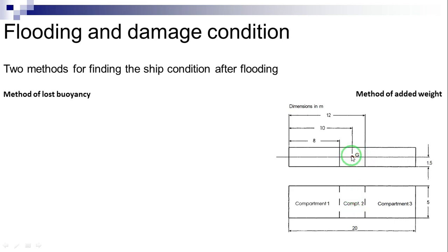Thus, the flooding of compartment 2 produces no trim. Also, the compartment extends for the full ship breadth and its flooding produces no heel. The only change of position is parallel sink. Thus, the complex calculations necessary for conventional ship forms, for large trim, or for unsymmetrical flooding do not obscure the principles, and it is possible to obtain immediately a good insight of the processes involved.